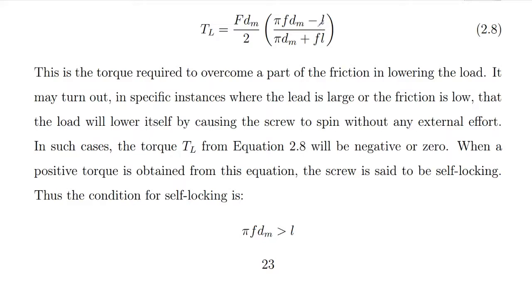Okay, and when the lead is large, or the friction is very low, you may end up having this expression here to be negative. Because in this expression, we have pi f dm minus L. If the lead is so large and it's larger than this expression, you are going to have it to be negative.